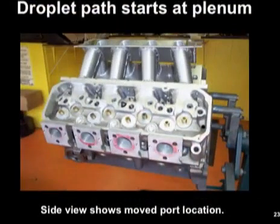Droplet path starts at the plenum. Side view shows the move port location. To give you an idea how much was added to the top of this head, I added over an inch of material to the top of these heads so I could get the ports where they needed to be. The original port laid over here, and all that material was added, and we put it over there.